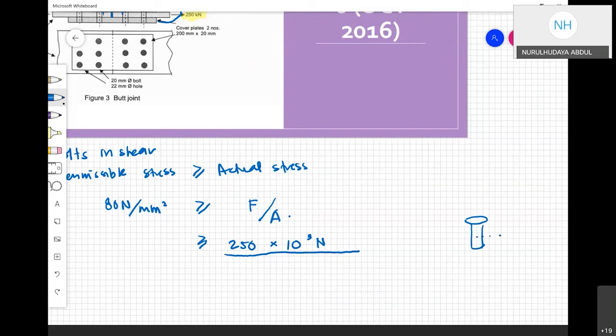for that, what causes shear. If you look at force divided by area, the area should be parallel to the force, like this. So it should be the cross section area of the bolt. You cut the cross section here, and you will get a circle like this. That is the cross section of the bolt. You need to calculate that area. To calculate a circle, it should be pi r square. So pi times the radius.